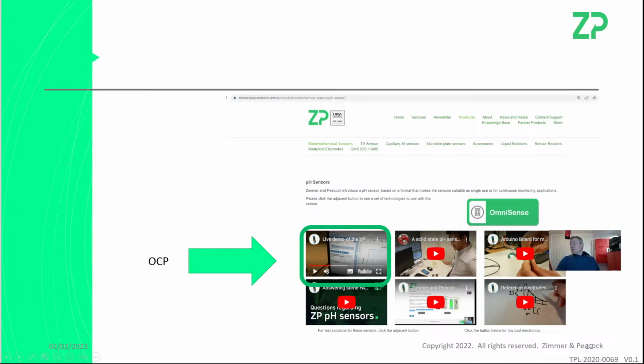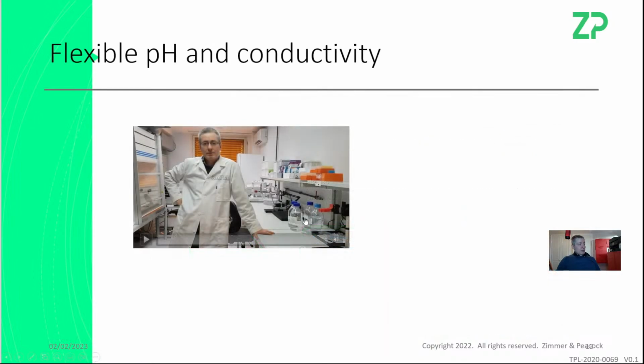The pH sensor, for example, is an open circuit potential measurement. So I put a link here. There's a video that shows us doing a lab experiment around that. We do cover pH sensing in our workshops, and that's an example of a potentiometric measurement, specifically open circuit potential, which suggests it's high impedance, and that is covered in our workshops.